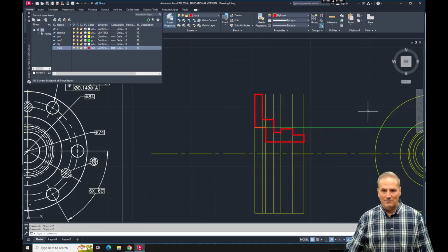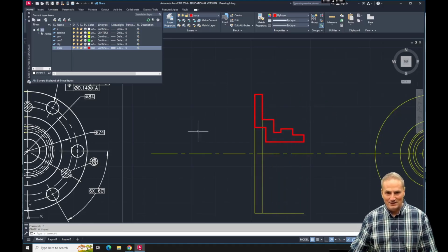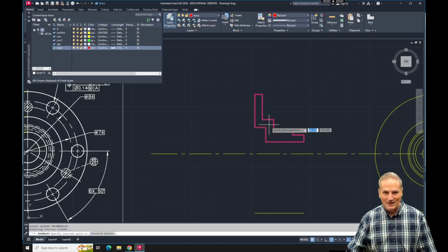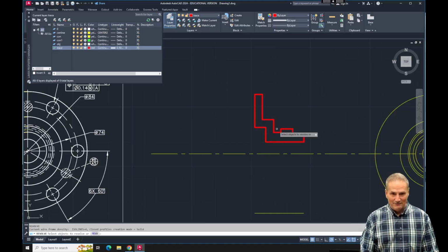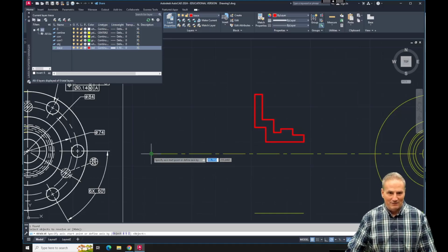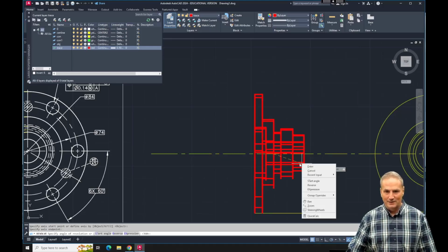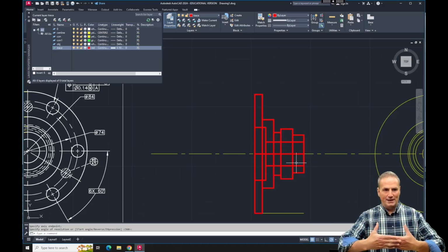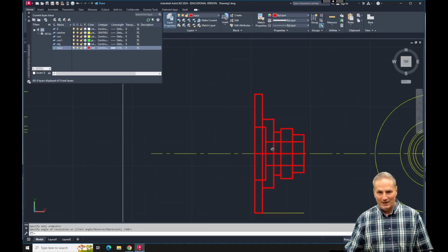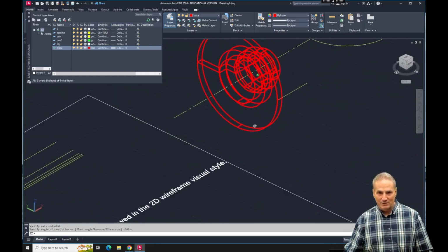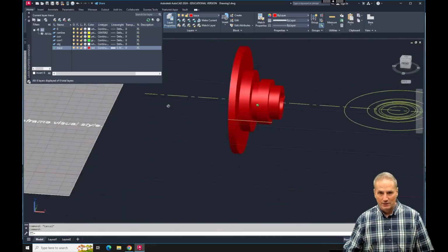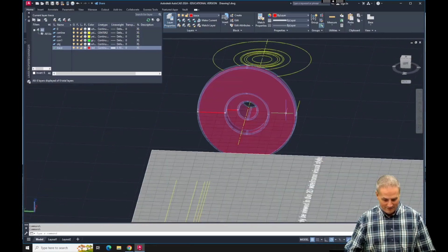A way to solve that problem would be this. Yeah, let me do this. Let me get rid of all that stuff. Let's get rid of this stuff here now. And I could do, what, -BO? I could click inside, say enter REV, L for last, and my revolution point is going to be here. Enter. And the reason that wouldn't revolve is because I probably had multiple lines on top of each other when I joined. But anyway, again, this isn't perfect here because we don't have the fillets and everything in that we should. But you can kind of see we get to the point where we have our part, right?